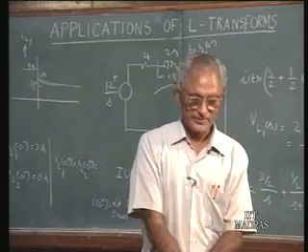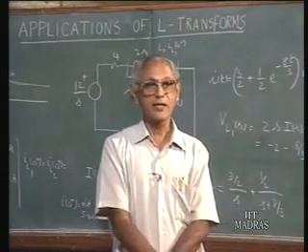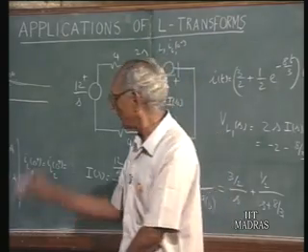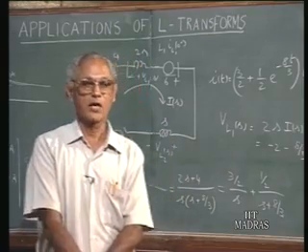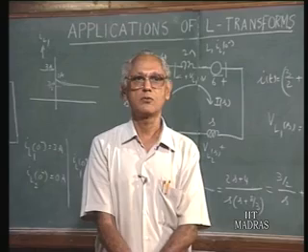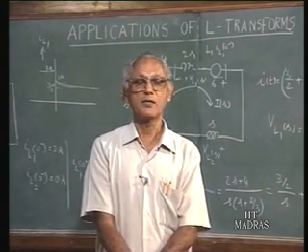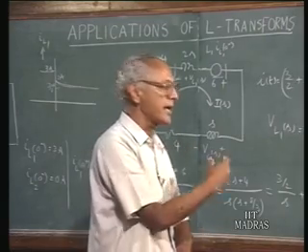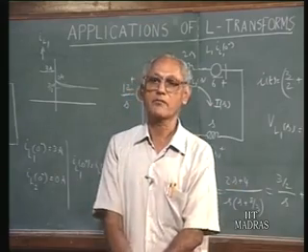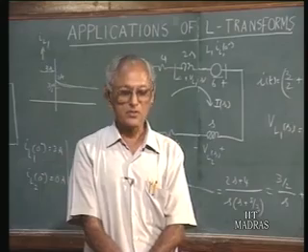But the main advantage of the Laplace transform technique is that the initial conditions pertaining to the system are plugged into the equations at the very beginning itself. Therefore, you do not have to evaluate separately the arbitrary constants that you have to do in the case of differential equations. And this is very important, because if the number of reactive elements becomes large, suppose there are 4 or 5 reactive elements and you have a 4th order differential equation, then you need to know 4 initial conditions, not only the initial value but the values of the first 3 derivatives.